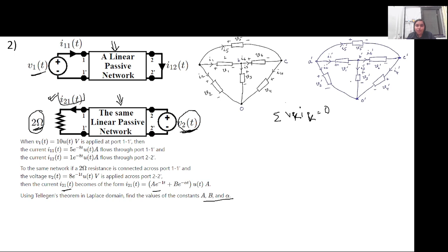And also, if these two circuits have the same topology, same topology means the way the branches are connected is the same, whereas the circuit elements, in this case for example this and this, may be different, but if they are connected in the same manner as shown here, what will happen is, for example, the voltage across this branch, which is V2, into the current that is flowing here, which is I2 dash. Similarly, the voltage for each branch of the circuit, that is to say that summation of Vk into Ik dash, where Ik dash is the corresponding current in the different circuit where the circuit parameter may be different in that particular branch, will also be equal to 0.